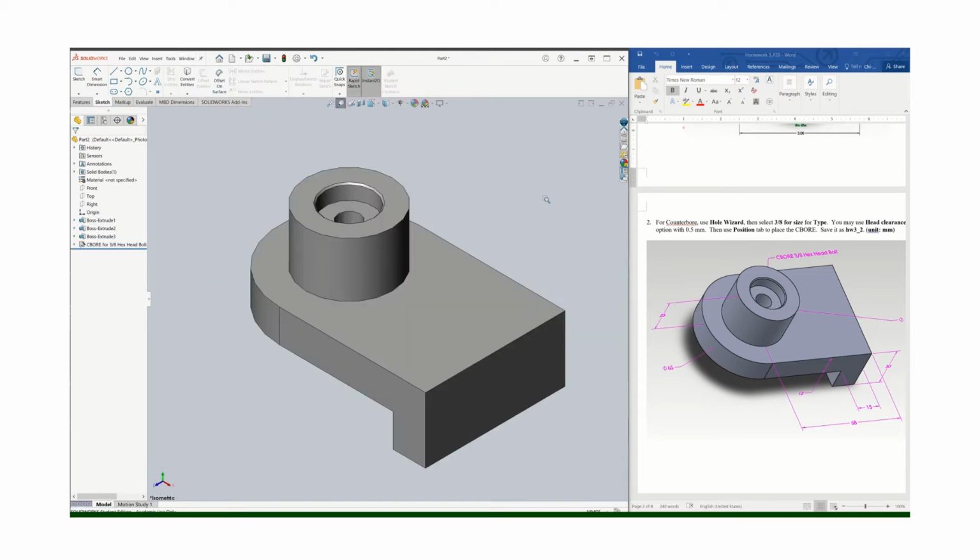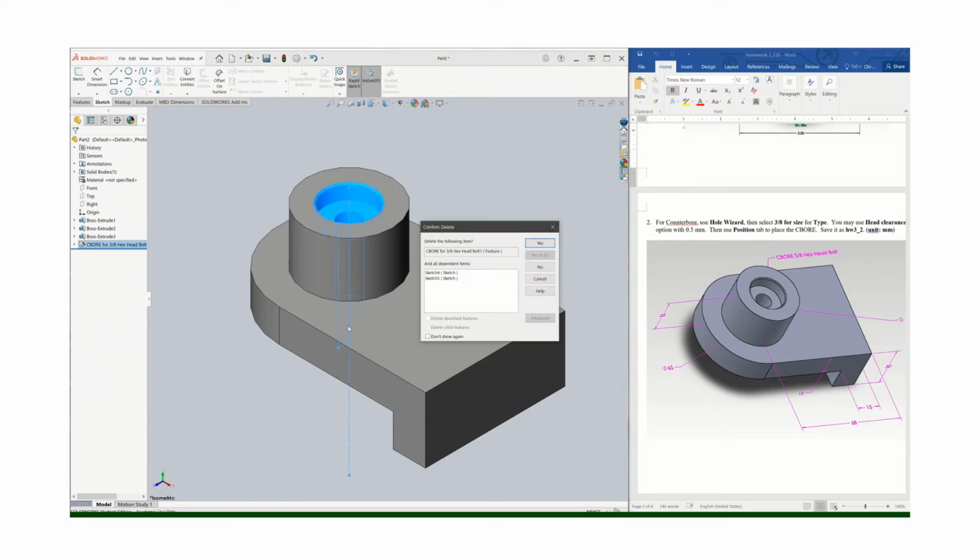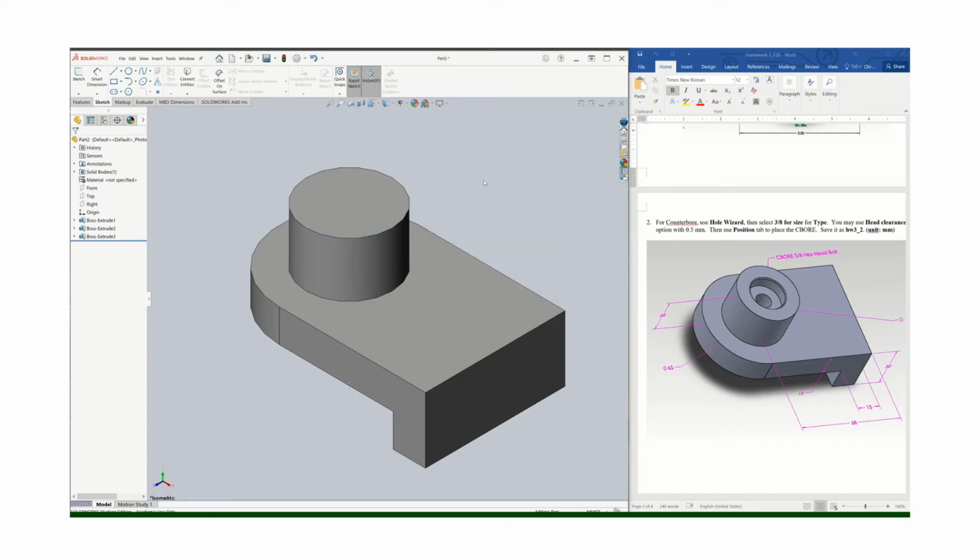the second part, that's what you have, and I already put the counterbore, but I would delete that one so that I could start all over. So now I create all the parts, and one thing that you have to know is I do not use the top plate for the base, I use the front side and have this L shape and then extrude in that direction. Many times, when you have an angled bracket or basically an L bracket, starting from that side is much easier.